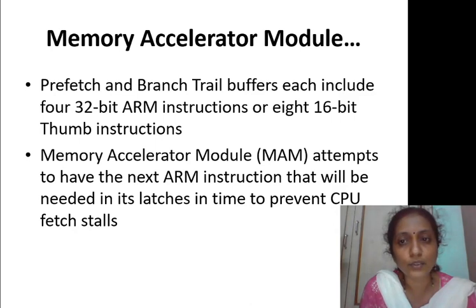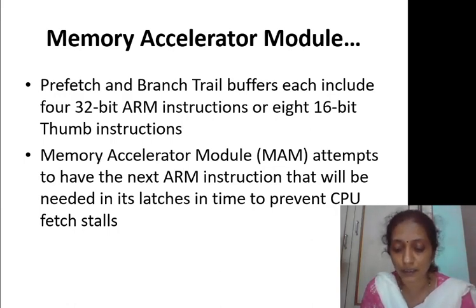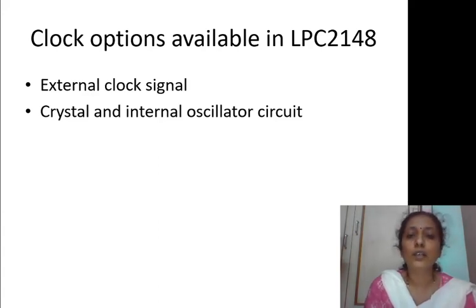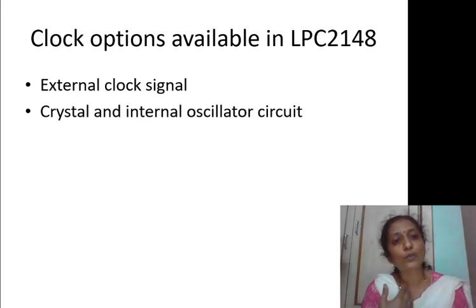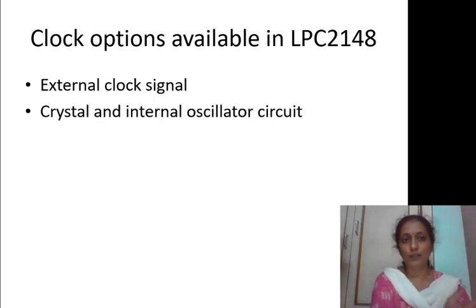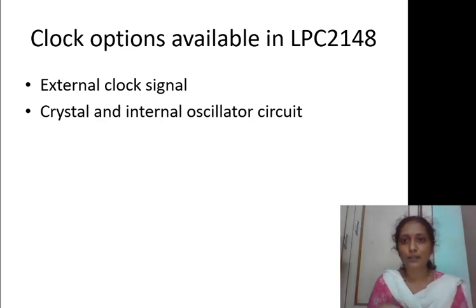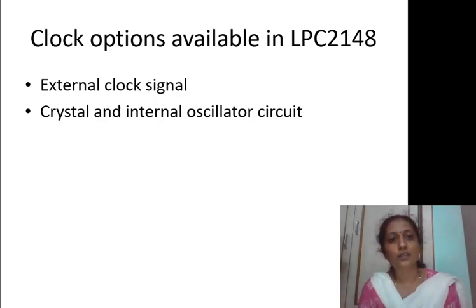Then we are going to study the next important part of the system block of LPC2148, and that is the clock signal. Okay, so you are already familiar with the clock signal of 8051. Same thing I am going to repeat here. In case of LPC2148 also, as usual, 2 options are available. One is you can use an external clock signal which is going to drive LPC2148. So you can give directly one clock signal from one clock source. You can take it and give it to the 2148.